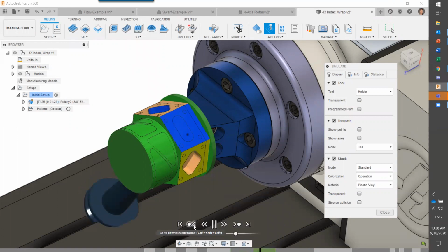And this is what order by tool is doing. If you recall, we machined out this pocket, we roughed it out, and then we did a finishing strategy, and then we went to this slot here, roughed it out, and then did a finishing strategy. Order by tool keeps the pattern so that you're using the same tool, and you're machining all instances that tool is going to be called out for. So we're machining all of these pockets because all of them are being machined with this tool. It's doing all of those first, and then it's going to transition over to the next tool.